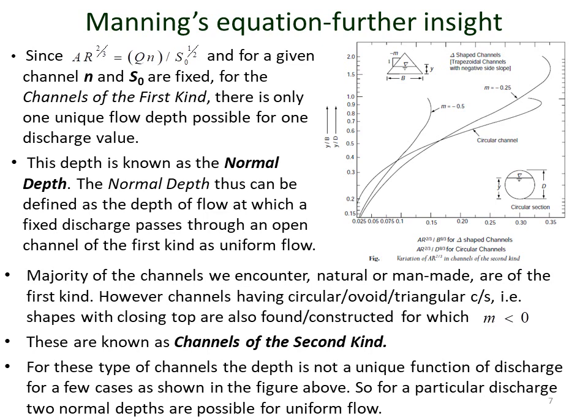Look at these diagrams: they are really non-linear, and one important aspect of this diagram is that in some parts of the curves, the flow depth is not a unique function of the section factor anymore.